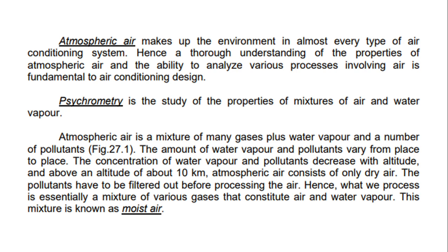Atmospheric air makes up the environment in almost every air conditioning system. Hence, a thorough understanding of the properties of atmospheric air and the ability to analyze various processes involving it is fundamental to air conditioning design. So, psychrometry is fundamental for designing an air conditioning system. In this, you are going to study the properties of atmospheric air and the water vapor present in that atmospheric air, which is called psychrometry. Okay. Various gases may be present in the air.